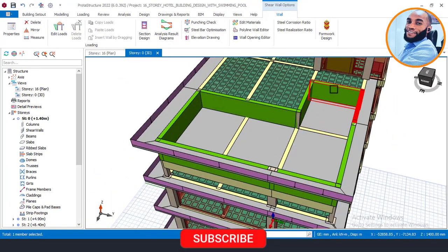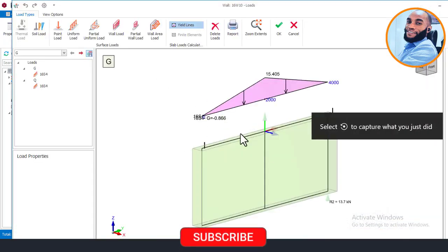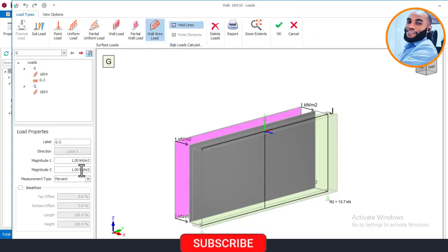And I'll come again right here, click on this place here, right click here, and then edit load. Okay, that's fine. Now come again right now, click on wall area load here, click on this and then come here and define 13.63, and also the same thing here, 13.63. So whenever you are doing your design, make sure you are careful when you are inputting your loads.